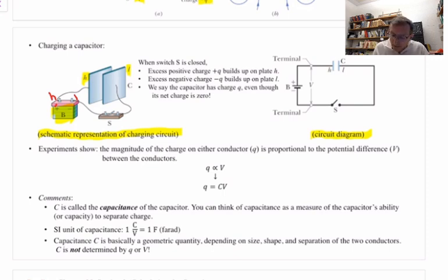All right, now, this shape here represents the battery. And it's got a short line and a long line. And the longer line is the high potential side, and the shorter line is the low potential side. They're labeled plus, minus. And then it represents the actual terminals of the battery, there and there. And the battery's job is to produce a certain potential difference across its two terminals. And that's what this V here represents: the potential difference across the two terminals of the battery, produced by the internal chemistry of the battery itself.